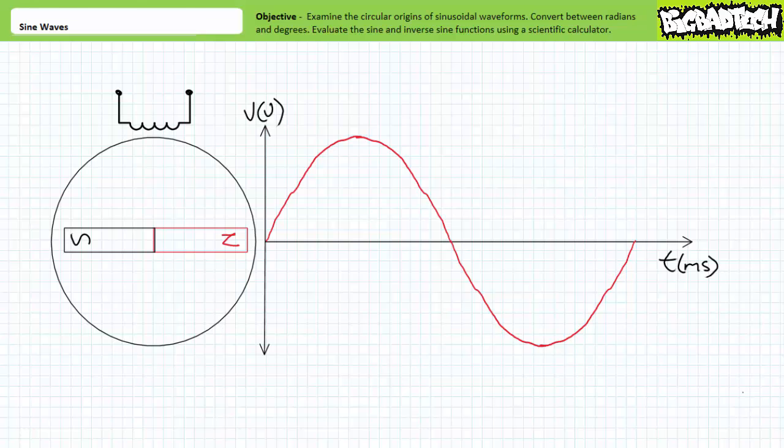Consider a generator shaft driven by some outside physical force like expanding steam, moving water, or blowing wind. Attached to this shaft is a magnet with a north pole and a south pole. This rotating assembly, consisting of the shaft and magnet, is appropriately enough called the rotor. Outside the rotor is a stationary set of windings called, appropriately enough, the stator.